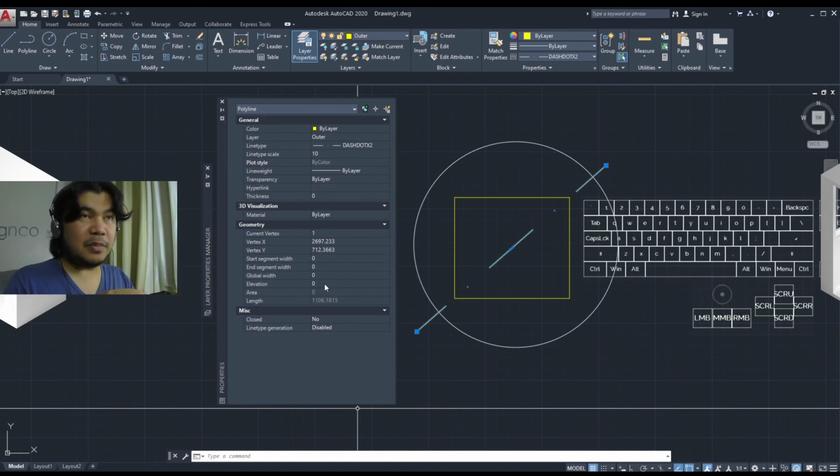A good rule of thumb is whatever scale you're using for your drawing, that is what you want the line type scale to be for most of your drawing. Because clearly, if you try and do details on the same modeling space, you'll need to modify either the line type scale of the items within that area or shift it to another file and modify the global line type scale on that. So there's plenty of workarounds here in AutoCAD.